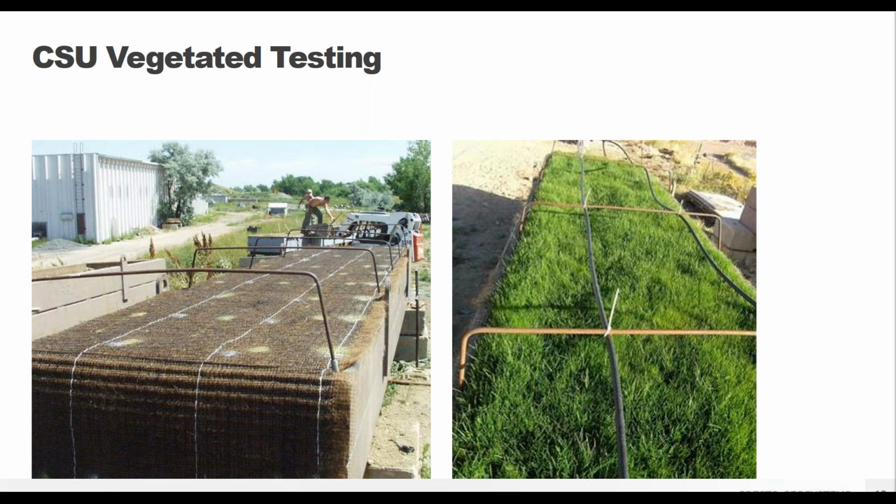So the testing consisted of using 6-inch deep GEOWEB panels filled with topsoil and then also using a surface protection method. So in this case, it was an erosion control blanket or a turf reinforcement mat. This is probably our most recommended cross section, that's 6-inch deep. And that's really because it does allow for deep root growth, that penetration of those roots of that grass and that vegetation to really get in place and hold itself there. You go with too thin of topsoil, sometimes vegetation is finicky and doesn't want to grow properly. So having that 6 inches deep is usually the sweet spot.